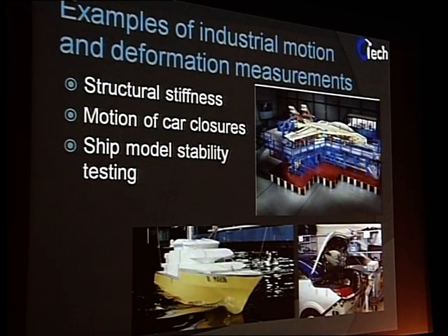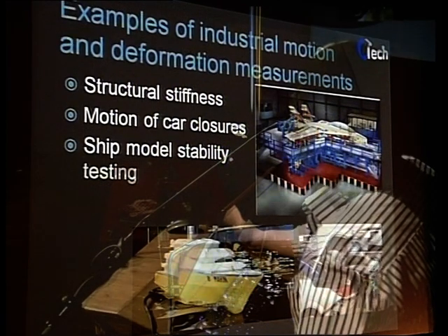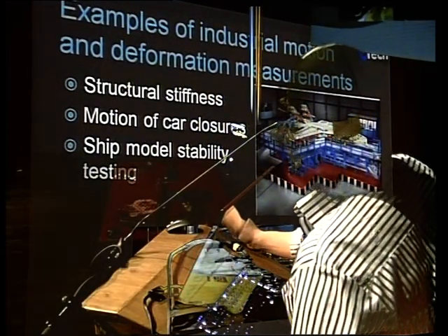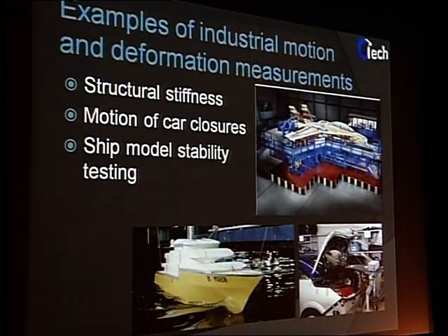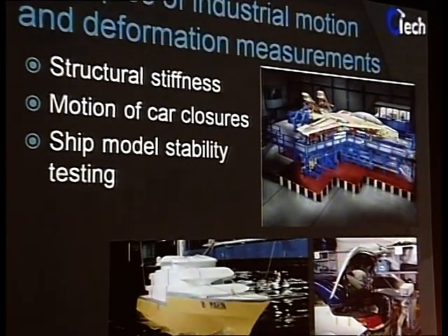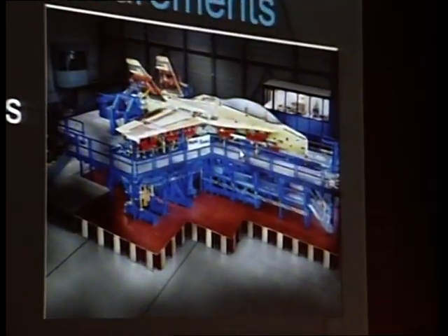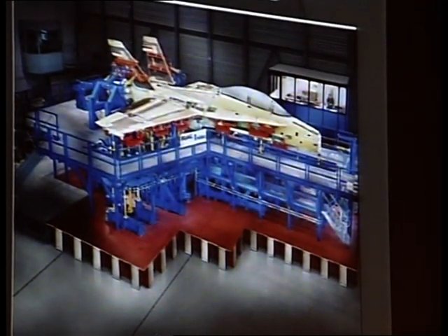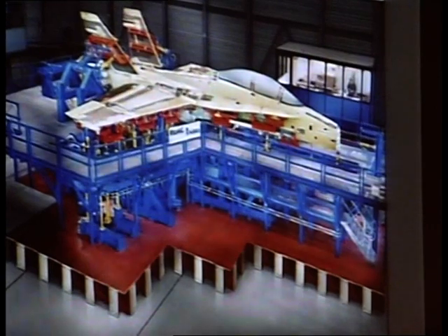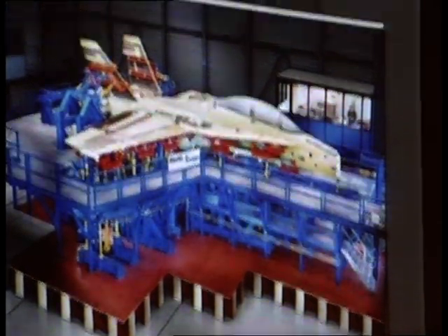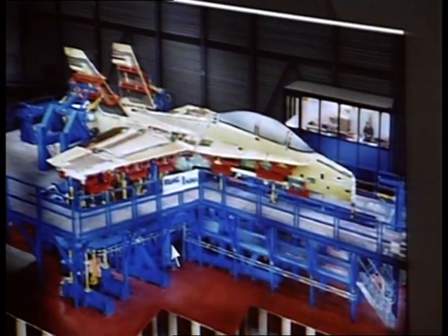So they started a test program where on one side they have virtual simulation using FE, trying to get a prediction of when cracks will appear, but don't trust simulation, do some real-life testing as well, and that's what you see here. You have an actual F-18 full scale, and underneath you can see all these yellow push rods, which bend the plane following two specific flight configurations. After 5,000 flying hours simulated, they compared simulation with real-life testing and saw cracks which were not expected.